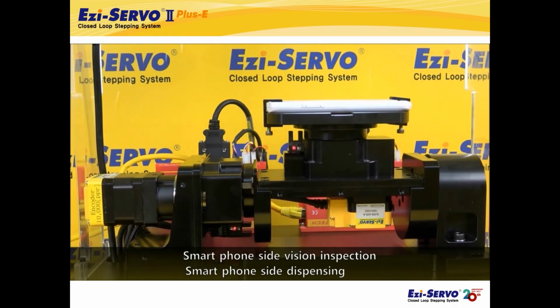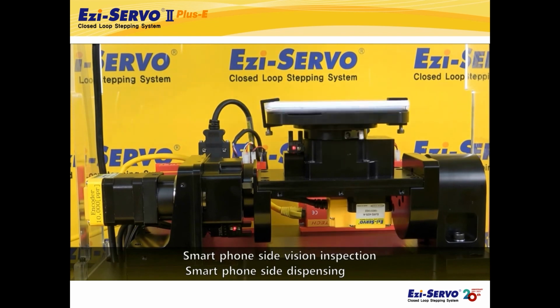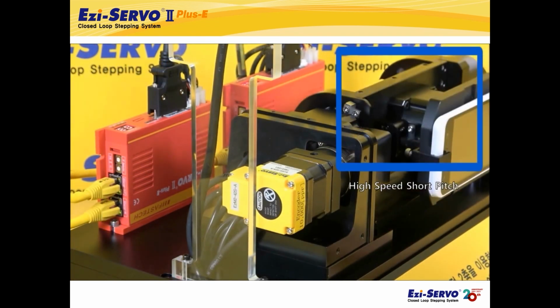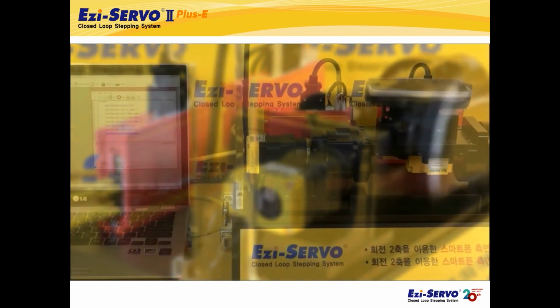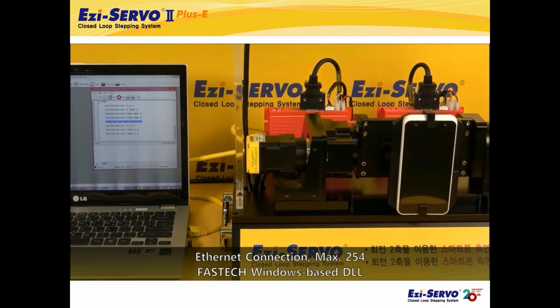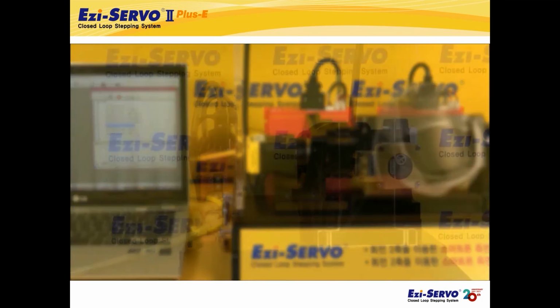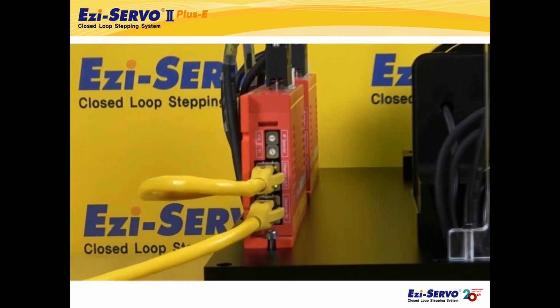Likewise, thanks to the holding torque characteristics of the stepping motor, vision inspection is possible without hunting even in high-speed short-pitch motion. This demonstration also shows that it is possible to simply control it with the API provided by FASTECH by directly connecting Ezi-SERVO Plus-E to a PC through the Ethernet port.